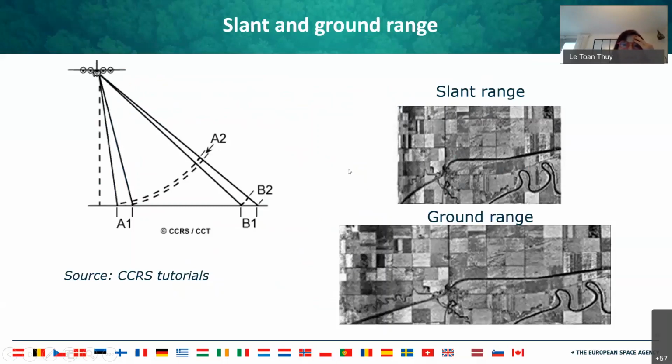The slant range is the part here in the slant direction, the side direction, and here near range, far range, and if you want to look at this part, A1 on the graph, you end up with something, A2 here, that is quite smaller because it's on the slant range, or the B1 becomes B2, and so the slant range is the same thing, but more compressed.